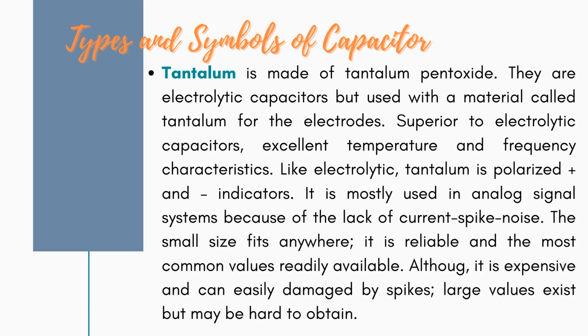2. Tantalum. Tantalum is made of tantalum pentoxide. They are electrolytic capacitors but use a material called tantalum for the electrodes. Superior to electrolytic capacitors. Excellent temperature and frequency characteristics. Like electrolytic, tantalum is polarized, with plus indicators.